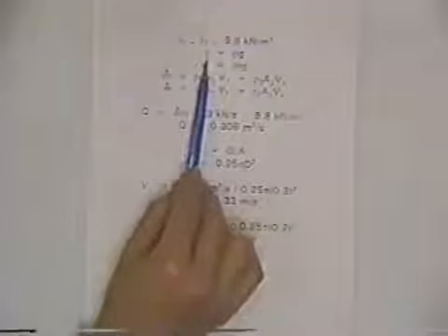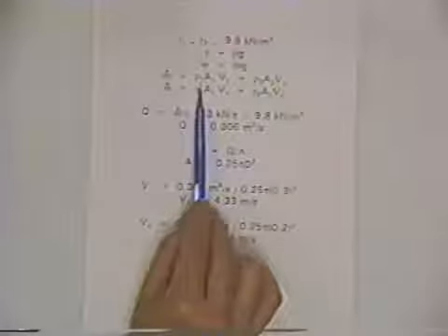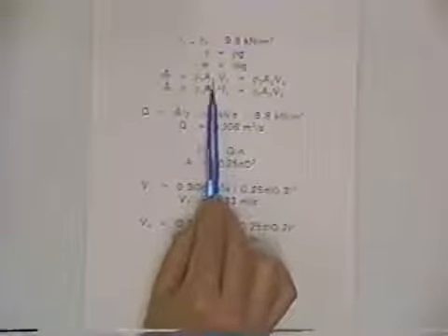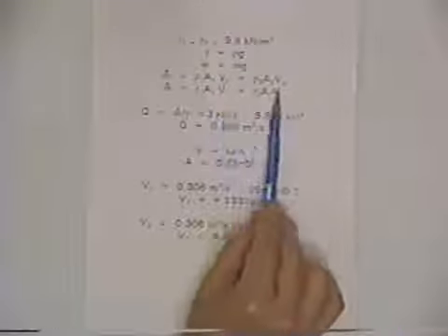And we recognize that conservation of mass can be related to conservation of weight, in the sense that the specific weight is just the density times acceleration of gravity. A weight is just a mass times acceleration. And so we like to write the conservation of mass as a mass flux is just the density times a volume, and the volume's an area times a mean velocity through the area. At one location in one pipe is the same as in the other pipe, pipe 1 and pipe 2, or the different diameter pipes.